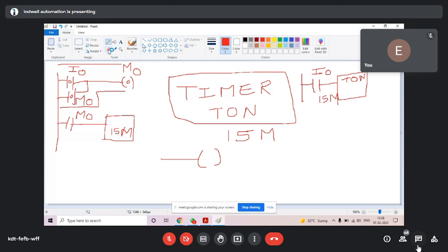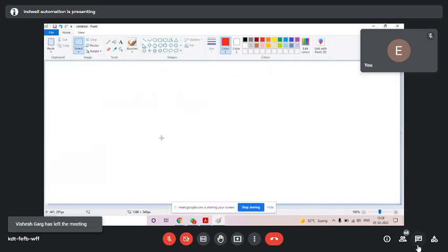Now you switch off push button. As this path is broken, is off, this path is not active. But M0 still gets supply from latch path. So M0 will continue on in this case. This is latch. So we latch for continue on. This coil will continue on because of latch. As this is continue on, this M0 contact will also continue on, and this timer can run. Okay, done. Next, I go for timer now.